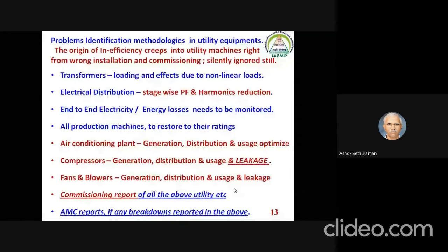The OEMs or the harmonic vendors, I don't complain about the vendors. When they talk, they want to do all the activities only in the powerhouse. Let them come to the field. You do the stage-wise PF improvement for a linear load distribution, and harmonic reduction has to happen in any of your motors if it is VFD driven. H5 and H7 are the main critical harmonics, and if the harmonics are arrested at source by the line reactor choke, at least 1/3 is arrested, 1/3 is controlled, and then you take it further to the SSB with detuned RCC, and then go to the powerhouse.